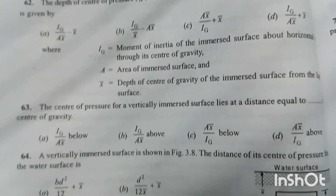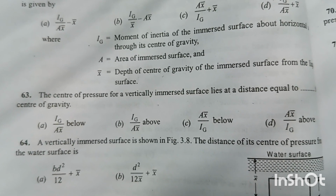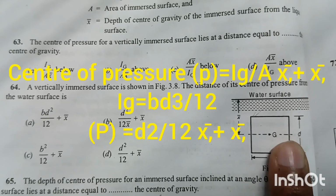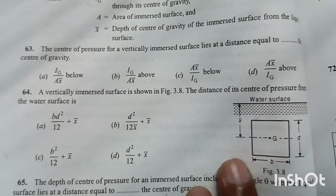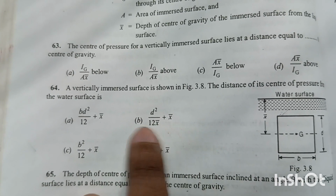Question number 63. The center of pressure for a vertically immersed surface lies at a distance equal to Ig by A X bar below the center of gravity. Option A is the right answer. Question number 64. A vertically immersed surface is shown in figure 3.8. The distance of its center of pressure from the water surface is. For this body, the center of pressure from the water surface H bar will be equal to Ig divided by A into X bar plus X bar. Ig value will be BD cubed by 12. If we put the value into the equation, we get the distance of center of pressure from the liquid surface H bar equal to d square by 12 into X bar plus X bar. Option B is the right answer.